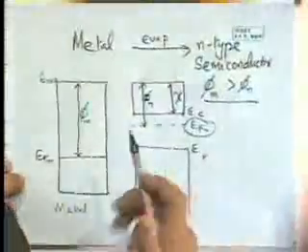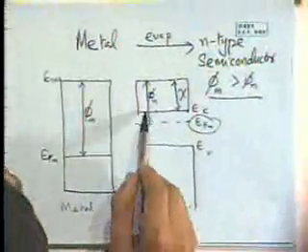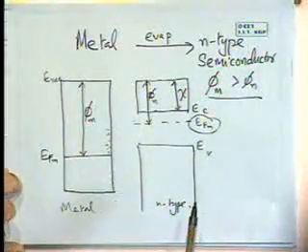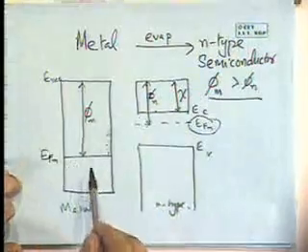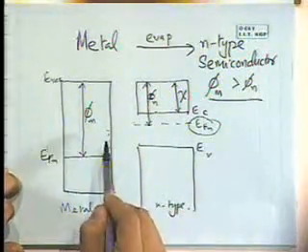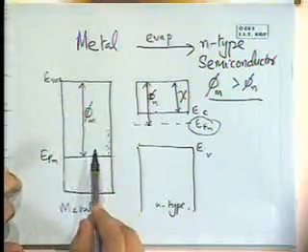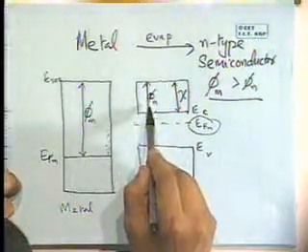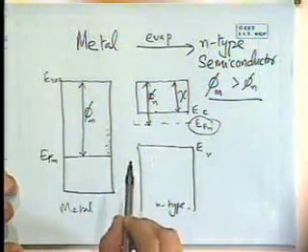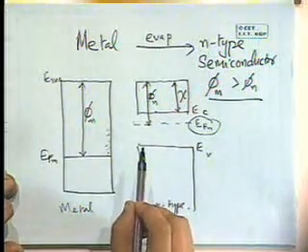And when they do that, we'll come to the final sketch, they start accumulating in the metal here. Okay, we've got electrons coming here. So this area is getting more and more negatively charged with respect to the earlier neutral metal. On the other hand, it's leaving behind in the semiconductor a core of positively charged ions.